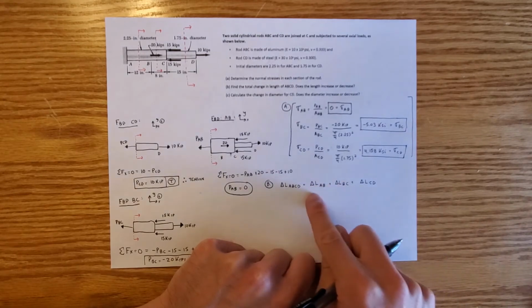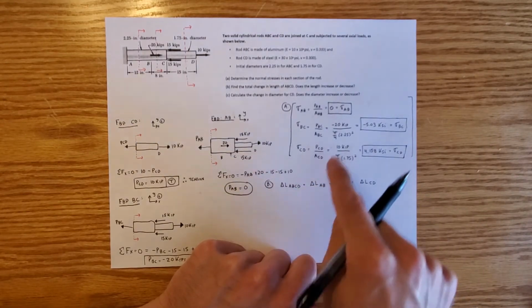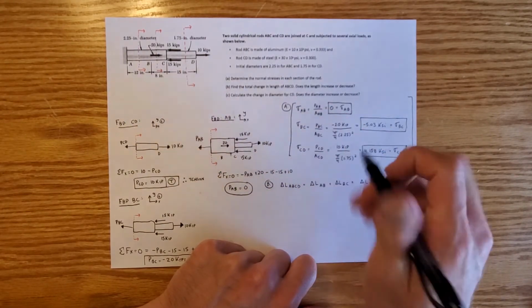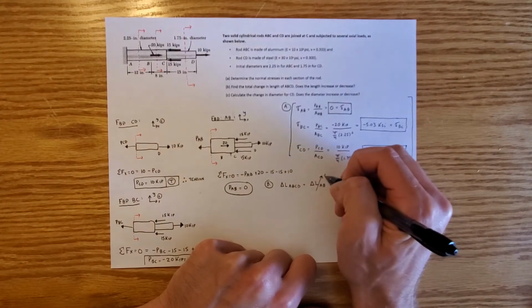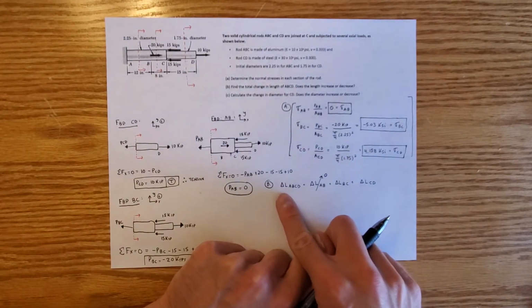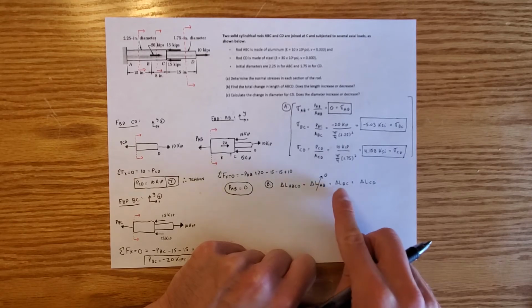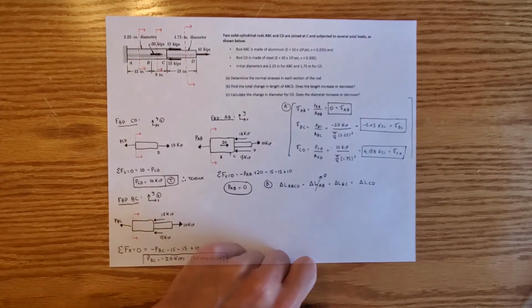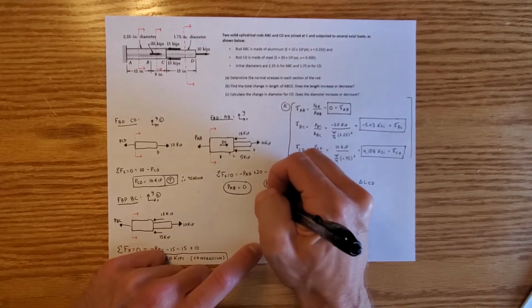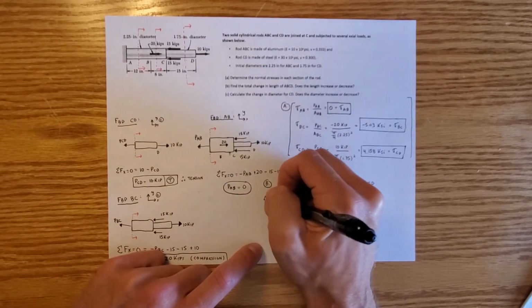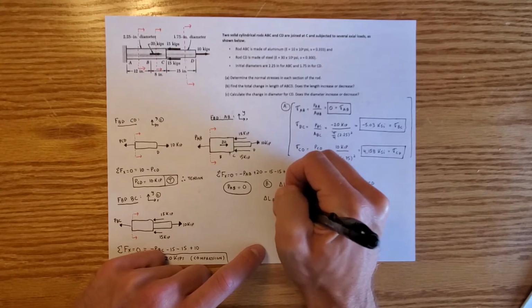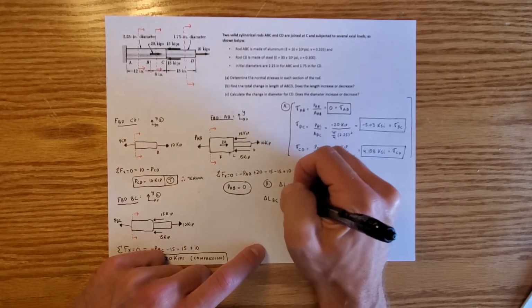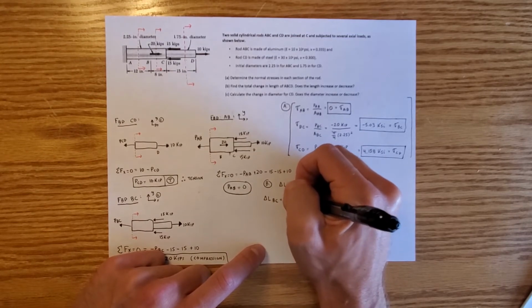Now, what we can do is realize that the change in length of AB is going to be 0 because it has no stress inside there, so it's not in tension or compression. So the change in length of our whole bar is going to be the change in length of BC plus the change in length of section CD up here. So now we can solve for each of those change in lengths. So the change in length of section BC is going to be equal to Fl, which is P of BC